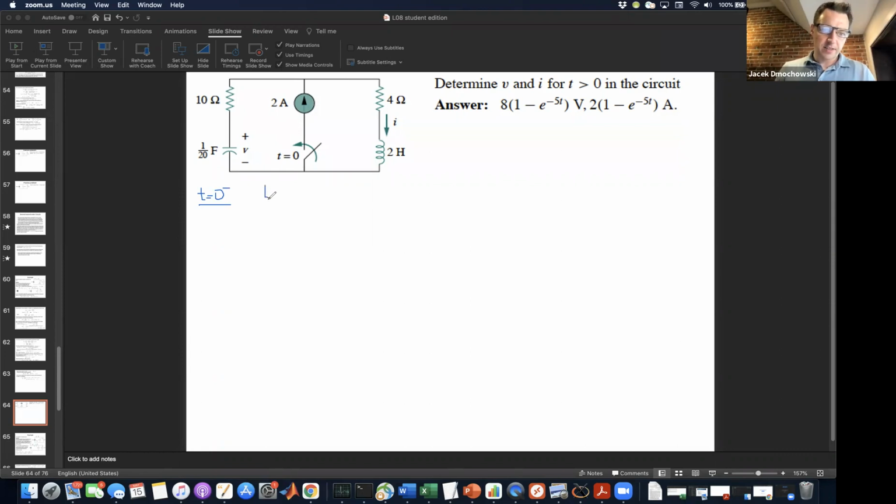So what we have is our resistor, we have our open circuit capacitor, and we have nothing in the middle because the switch is still open. We have our resistor, and we have our short circuit inductor, right? Our inductor is here, and it's short-circuited because nothing in the circuit has changed for a very long time.